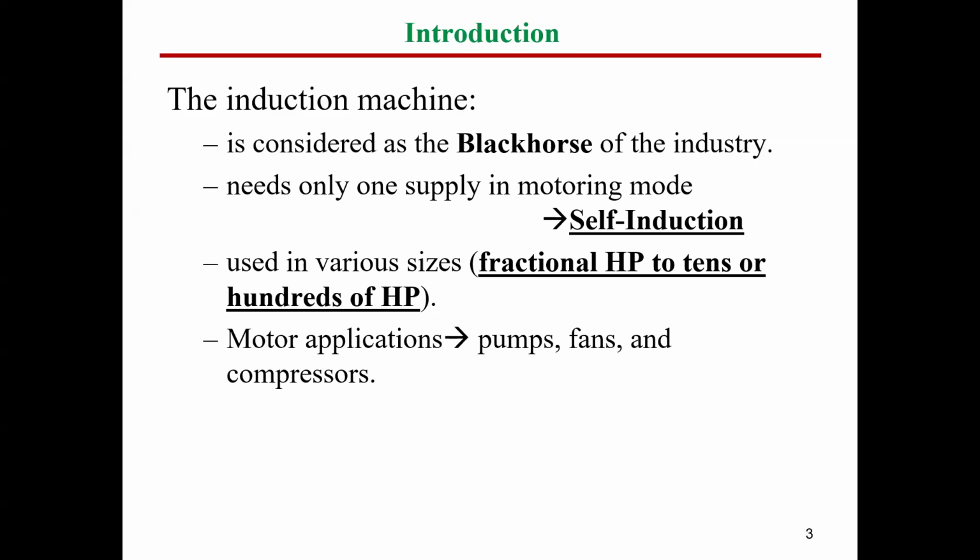What are the applications we prefer to use the induction motor with? We have, for instance, pumps, fans, compressors, and we call these types fan load machines, or fan load types. What is the fan load type? Fan load type is where torque is proportional to the square of the speed.